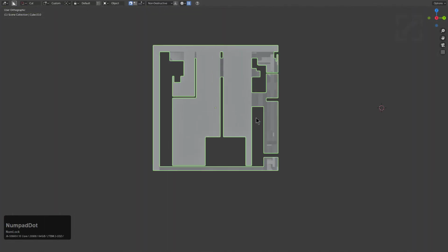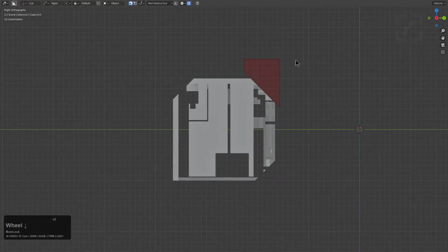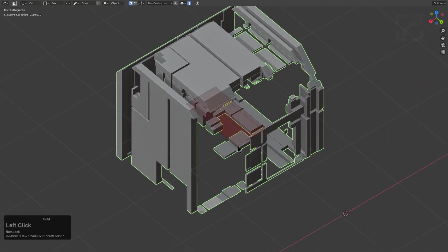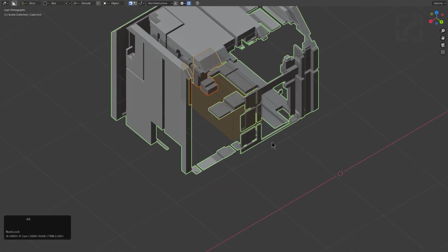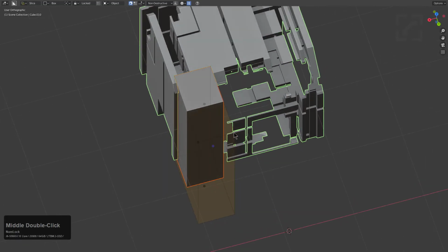So I'll select this, press Alt-H, and we'll just go in here, just get random with it, and do a cut here, also get random. And thanks to things like recut, like right here, a cut didn't work out, so I could press G to move it, and then double click to apply that. But because of recut, I can draw a cut, bring it down, press X to turn it into a slice, press Alt X to turn it into a recut, and cut back what I lost originally from this shape, from all the custom cut action.